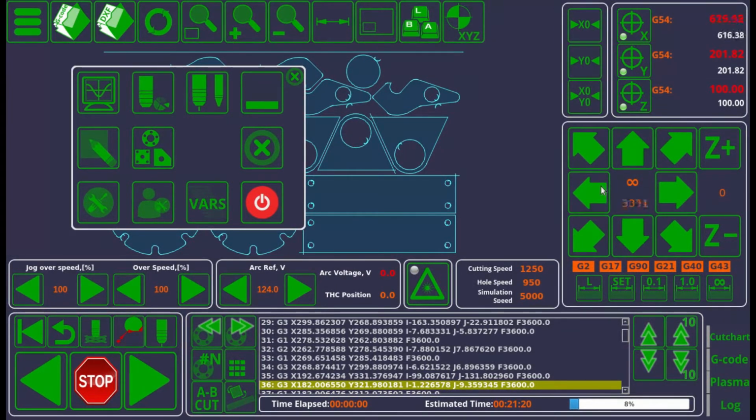And the fact that the on-screen coordinates are moving does mean that the controller is properly connected to your computer. However, when the controller is sending the signals over to the machine, something is happening. So typically the solution to that issue is to check the pulse width, or the width of the signals that your controller is sending over to your machine.